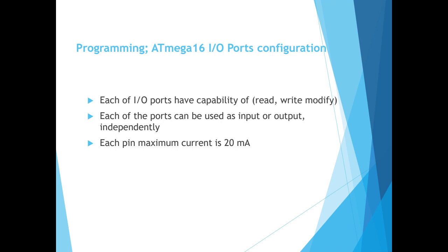Now, after talking about different issues of the microcontroller, and also having a review of the C language, I want to start coding our AVR microcontroller. We said that we will work with Atmega 16 or 32. But for coding, we need to have the input-output configuration at first. Each of the input-output ports has the capability of read, write, and modify.